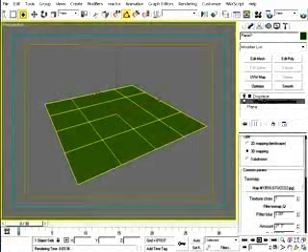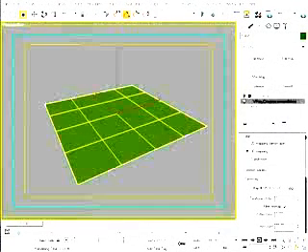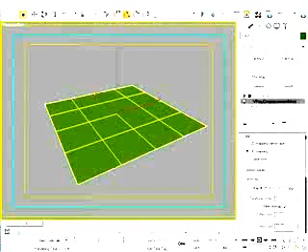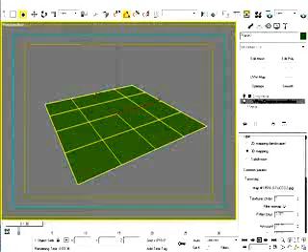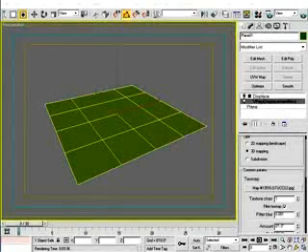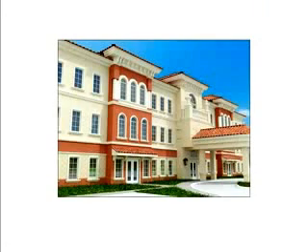Another great way to create the appearance of 3D grass is with the use of the VRay Fur feature. And as the name implies, it's a great choice for creating hair or fur on characters, but I personally only found an efficient use for this feature on two specific object types, shag rugs and grass. And although its practicality is fairly limited with these two particular object types, it's quite handy. Here's an example of the VRay Fur used on grass, which I probably made a bit too long for this image, but it nonetheless demonstrates its use pretty well.